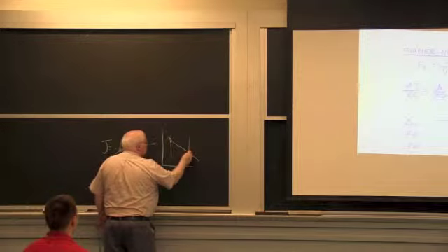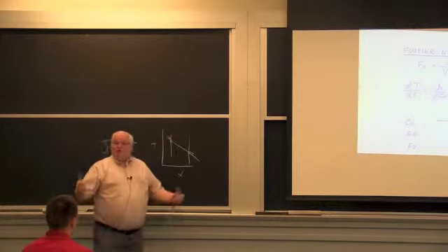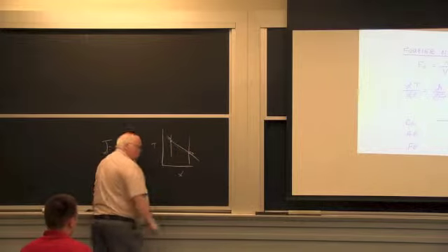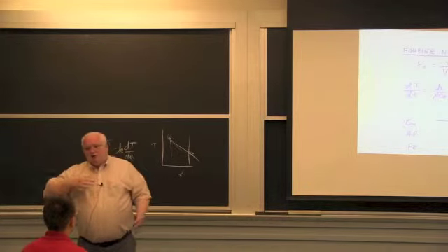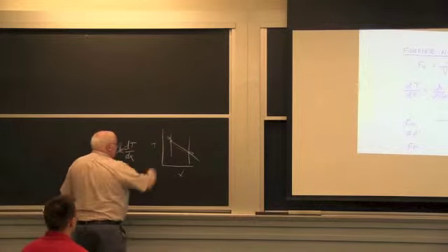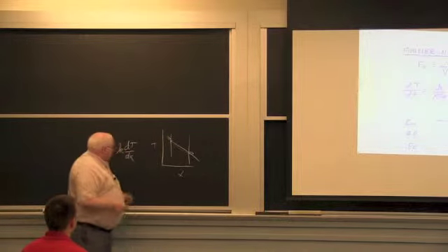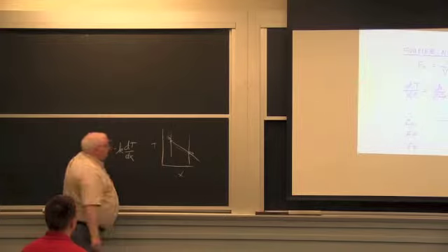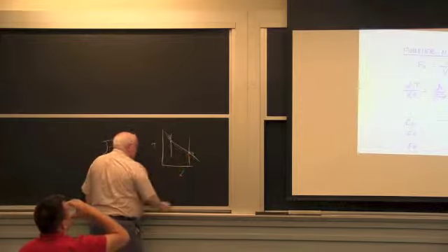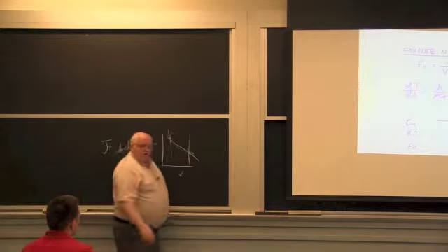The heat in equals the heat out. It's steady state. You get a uniform profile. And if you go to cylindrical coordinate systems, you're going to get something that has a curvature to it. Okay? Because your area is changing as you go out radially. Right? So things do change in different coordinate systems, and there are whole textbooks that take Fourier's first law or Fourier's second law, and the second law basically just says, well, let's have more heat coming in than going out, and how does heat accumulate in here, and how does the temperature change with time?